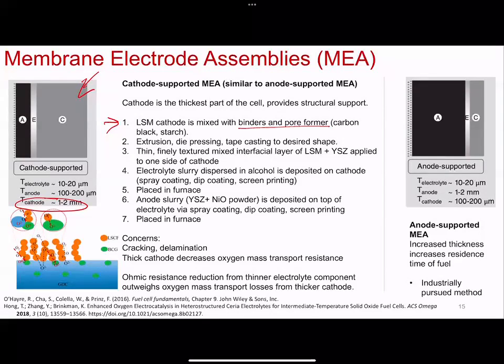If you mix in a little bit of polymer of the right size, when you heat up your assembly to assemble everything together, at 600, 800 C or whatever, the polymers will evaporate, or you'll burn them off essentially. And so you're left with a pore size that is the dimension of the polymer that you selected.